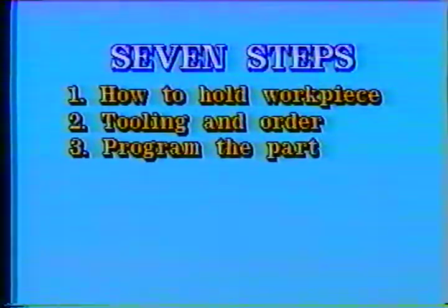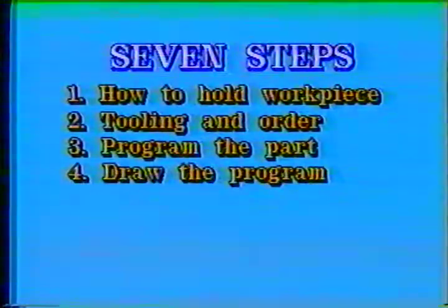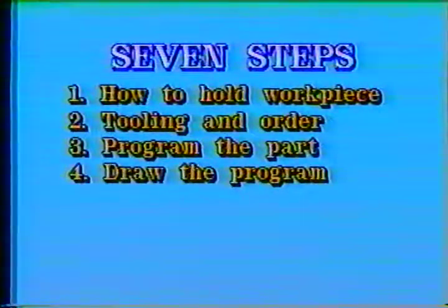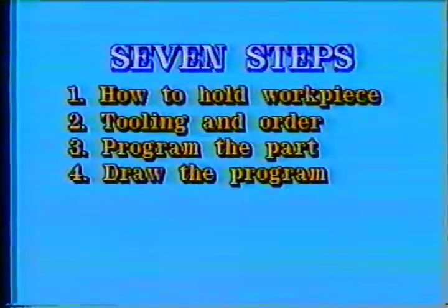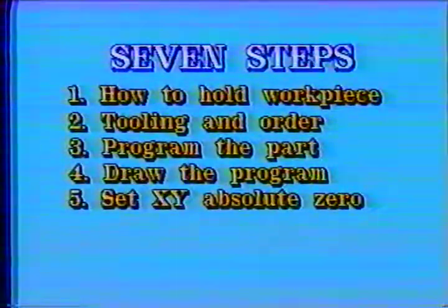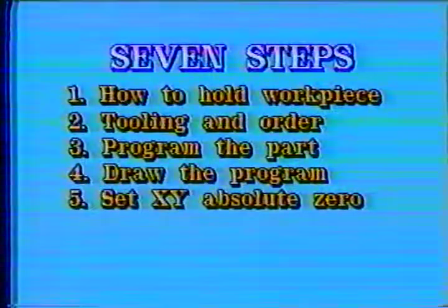Step 3 is to actually program the workpiece. And step 4 would be to draw the workpiece using draw graphics on the control to find any mistakes that you may have made. Then we get into the setup of the workpiece, starting with step 5, defining X0, Y0,